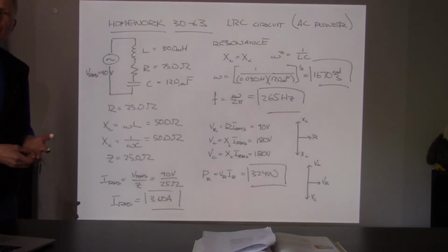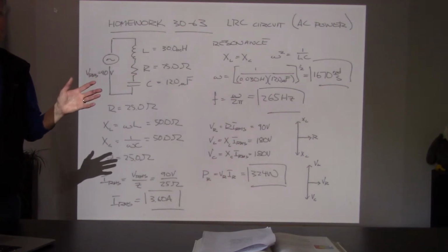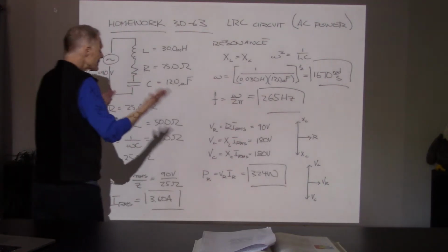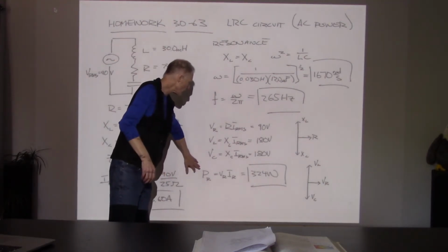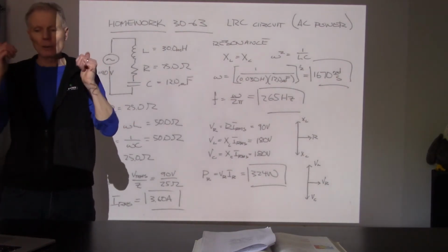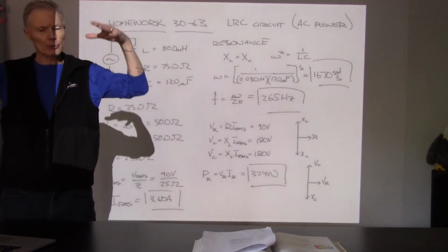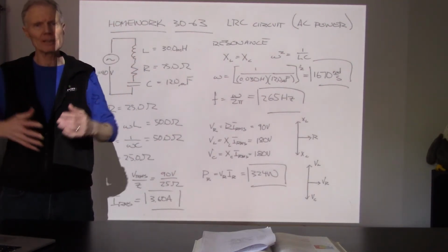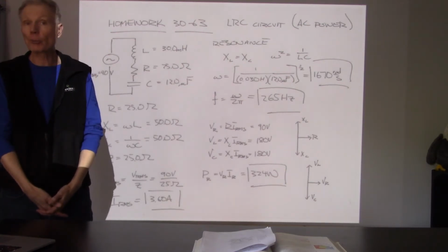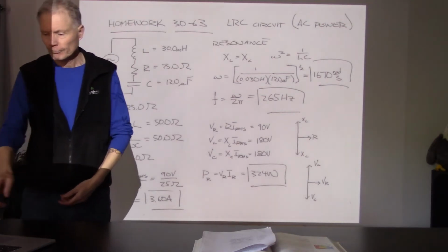With the capacitor and the inductor, we can't use that anymore. We have to average over voltage and current, which are 90 degrees out of phase with each other. At least averaged over time, that will work out to be 0. So the capacitors and the inductors acquire some energy and then release it. They energize and de-energize, energize, de-energize. The resistor is going to consistently take electrical energy and convert it to thermal energy.